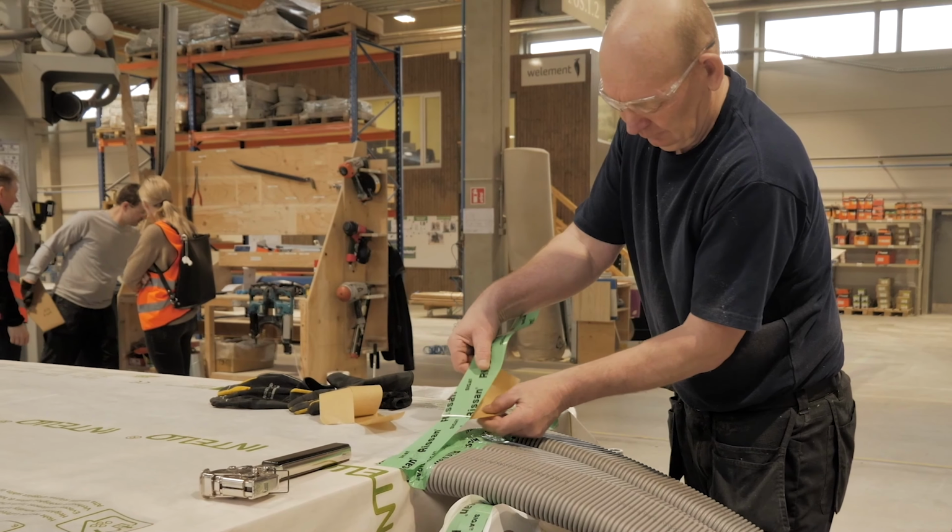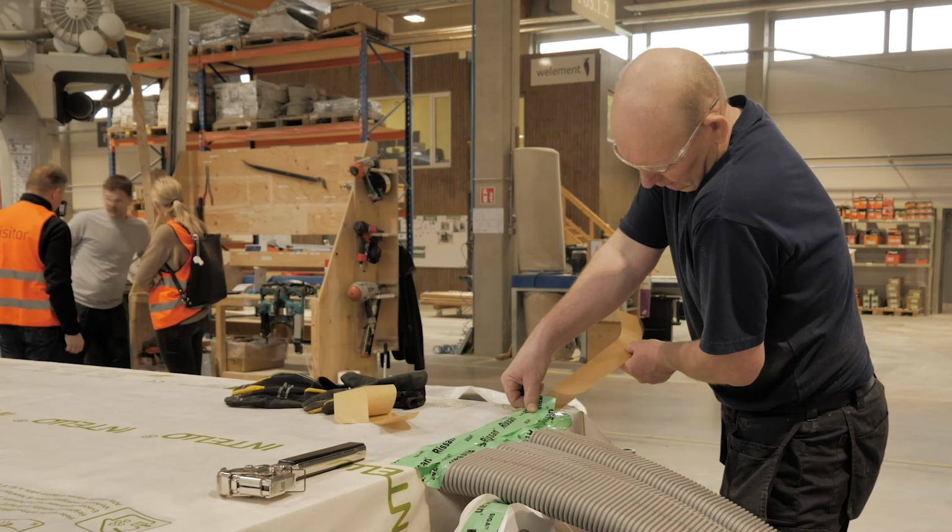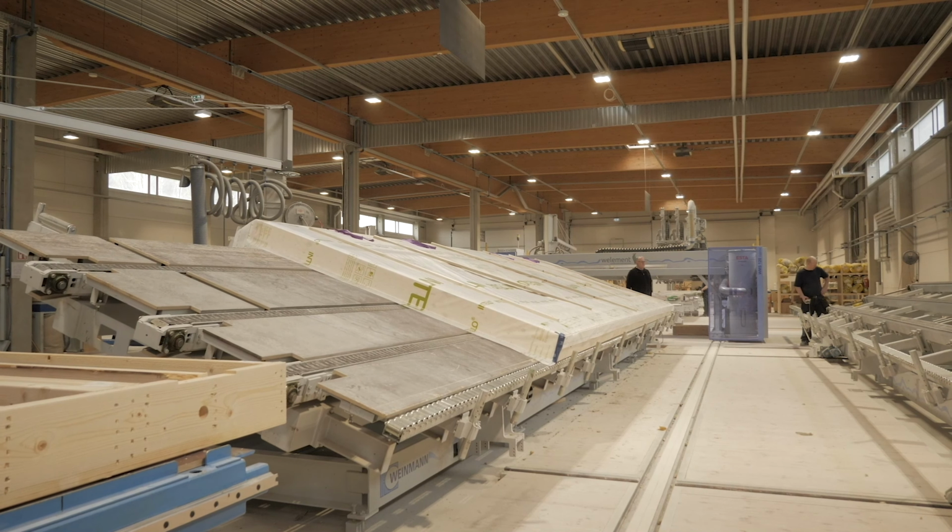If the vapor barrier is firmly attached and secured, turn the element over and check that the element meets the established tolerance requirements by measuring the dimensions of the element. If the diagonals meet the requirements, proceed with the next steps. Adjust the insulation edges to be flat with the frame.